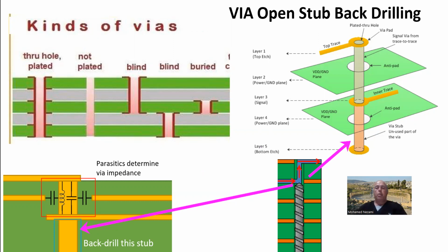With an open stub, you can see that the impedance, as you vary the stub length, can be anywhere from inductive, to, at quarter wavelength, because it's an open load, a short, and then on the other extreme, capacitive.